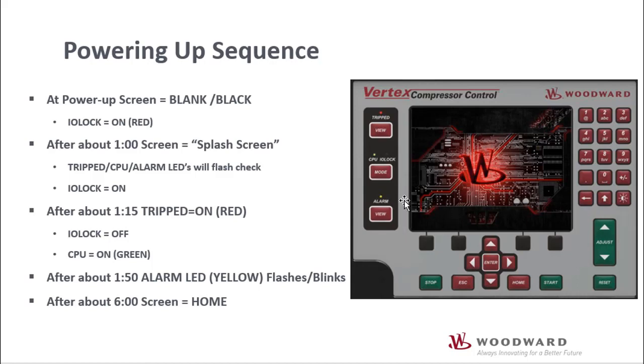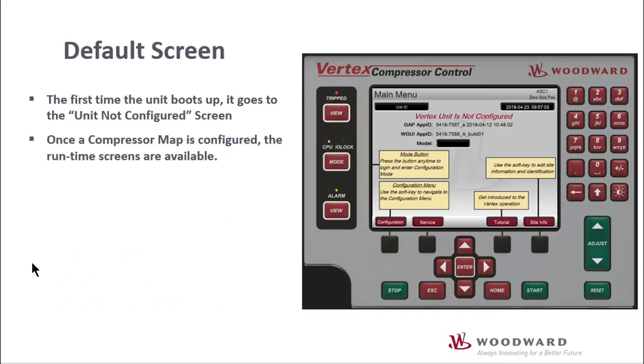If you ever get to the point where the alarm LED is solid and the splash screen is up, that means that the GUI is either stopped or something occurred during initialization and it wasn't able to launch. So it does take a little bit of time to bring the GUI up. After about 6 minutes, the screen will go from the splash screen and into the home screen.